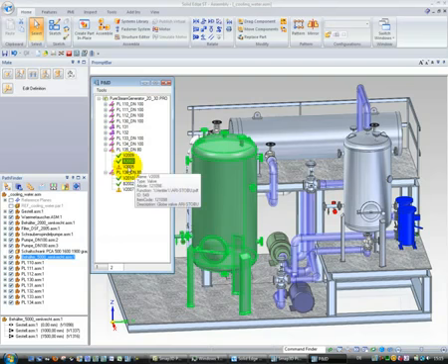Theoretically, we can do the same workflow with the next entry, which needs to be created in our 3D assembly. But if we look at the information displayed from the Pmid, we can see that this is a valve. And a valve you normally handle differently than outer equipment like a vessel or a heat exchanger or similar things. A valve normally belongs to a pipe spec, and a valve will normally be placed into a pipeline when the pipeline exists, and then it normally belongs to the inner equipment. So this I will show you in a later step when we have created the pipeline itself.